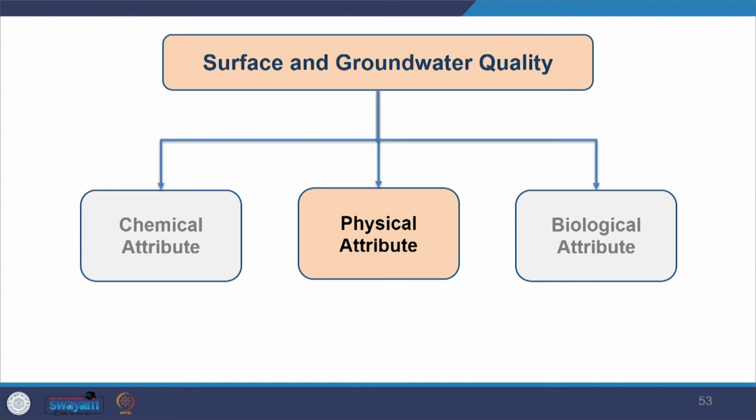These particulates range in size, such as silts, coarse sand, gravels or even boulders. These bed load materials can move when the flow of water exceeds a threshold limit. Flow of water depends on both channel slope and discharge.